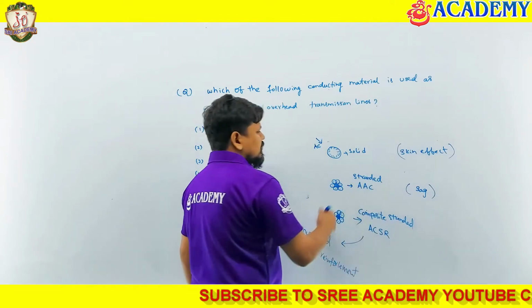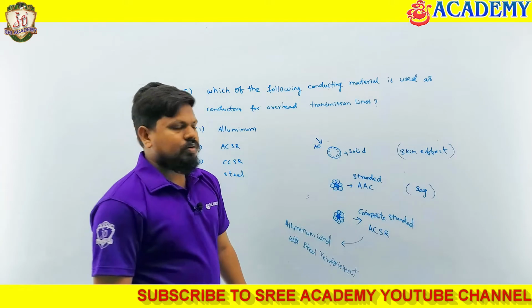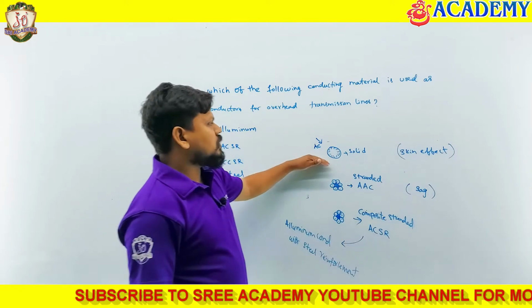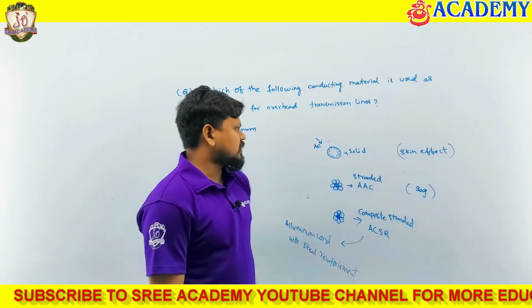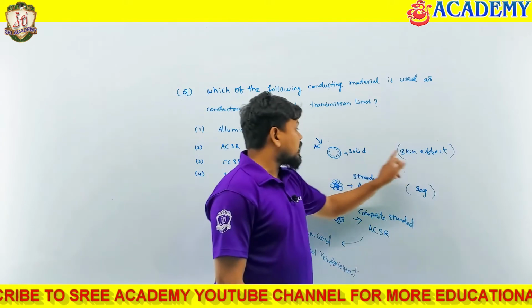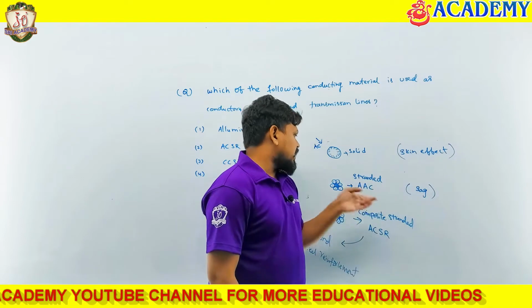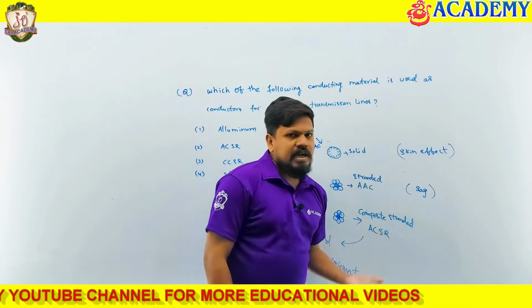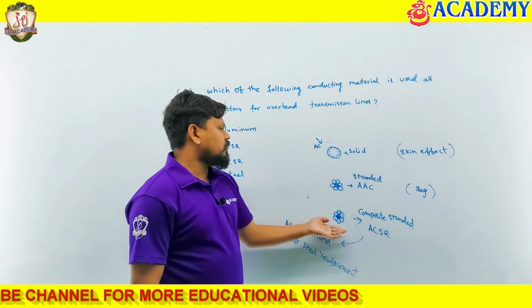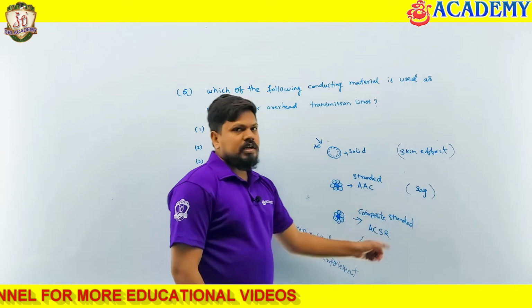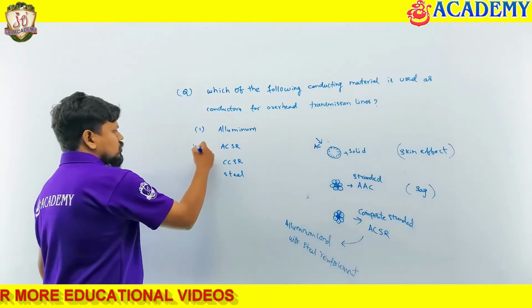With this one, sag will be decreased. So what is the problem with solid conductors? Skin effect is more in the solid conductor system. What is the problem with AAC conductors or stranded conductors? Sag is more. To overcome that we have to use composite stranded conductors, so we have to use ACSR. This is the answer.